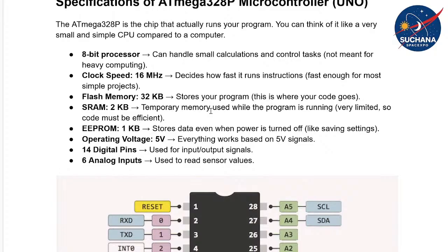So the first thing, we have memory limitations, and then clock frequency. I already told you different microcontroller architectures have different clock frequencies. Arduino UNO has a little bit lower clock frequency, 16 megahertz. For a simpler project, it's fine. Sometimes we may require higher frequencies, where we need to execute instructions very rapidly, and in those situations it may not be suitable. Clock speed is one of the important things we need to consider.